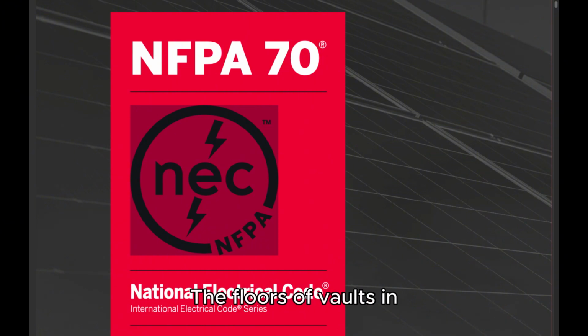2. Floors. The floors of vaults in contact with the earth shall be of concrete that is not less than 100 mm (4 in.) thick, but where the vault is constructed with a vacant space or has stories below it, the floor shall have adequate structural strength for the load imposed on it and a minimum fire resistance of 3 hours. 3. Doors.